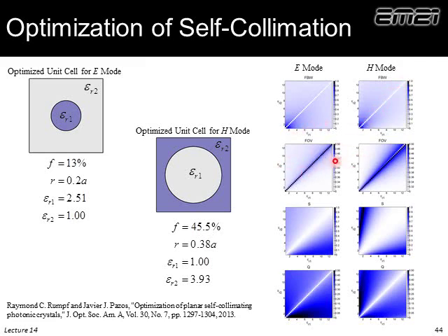Now let's look at what happens with field of view. This is how much the beam can diverge that would still self-collimate. Well, here we actually get the widest accepted angle for the highest dielectric constants. And in both cases, we actually prefer the epsilon 2 to be the highest. But field of view now wants to see high dielectric constants. Bandwidth wanted to see low dielectric constants.